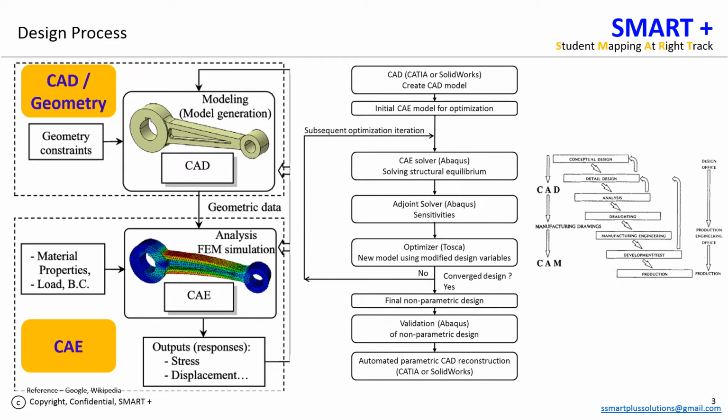So what is the design process? Generally we receive a CAD, also called a geometry. Then the design engineer models this 3D CAD data in software, maybe Unigraphics or CATIA. Then in CAE we have to mesh it with small elements which have nodes and elements, and split these components into small parts.